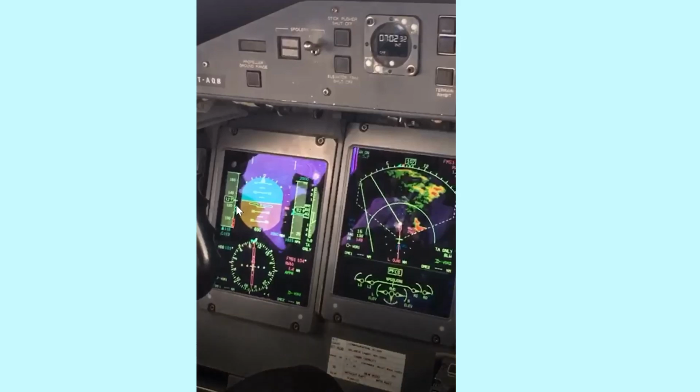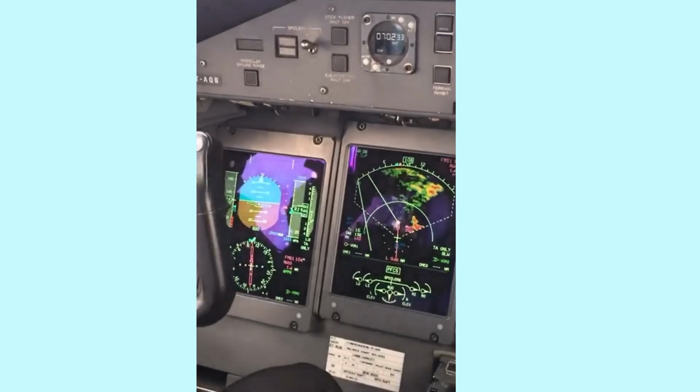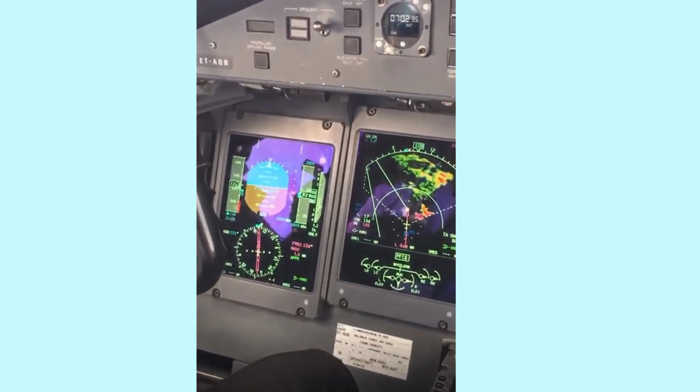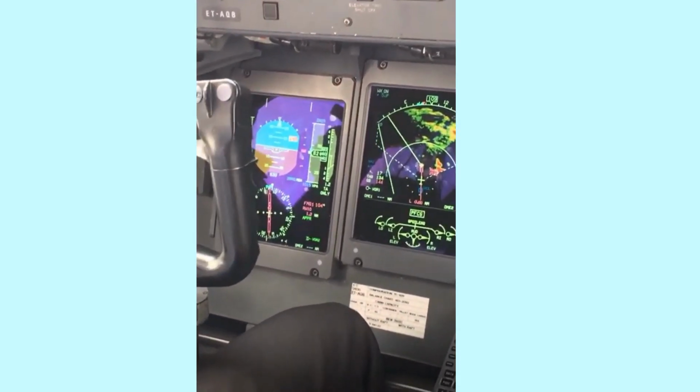I hope this idea is making sense to you, and also how to keep the pitch between 600 and 800 feet per minute by looking at the black wing bars to be between the horizon line and the negative 2.5 degree line. So let's continue and see how far we are getting. And otherwise, that's basically about it for this presentation.